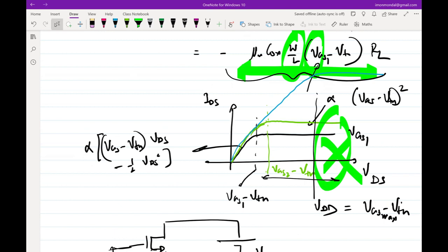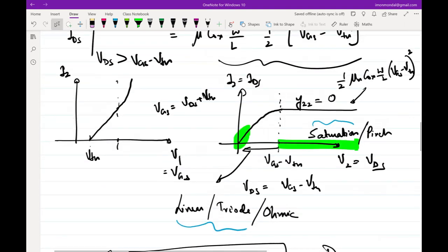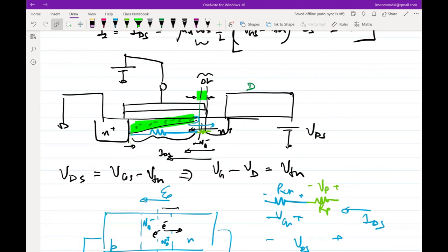Yes. So his question is more on the device side. One of the reasons we have a limitation on this maximum VDS is basically breakdown. Even when you are applying a VGS, there is an electric field, and whenever you are applying a VDS, there is an electric field. There's a vertical electric field, there's a lateral electric field. And the value of the electric field cannot really go to infinity, right? Because ultimately you have a lattice underneath, it will break the lattice. So there is a maximum electric field that you can apply.